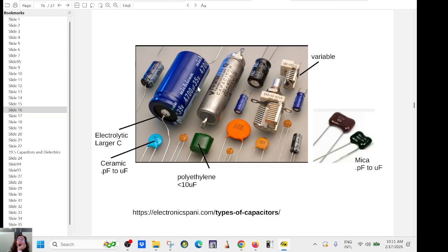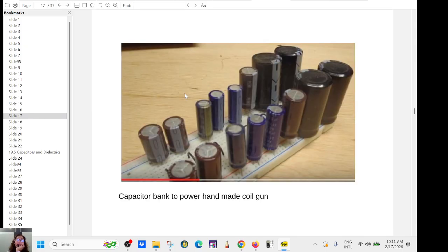You have to be careful to read the maximum voltage here. If you go over that, it pops. It's a polarized capacitor. If you don't plug it in the right way, it can also get upset. So it's very sensitive. It has feelings.